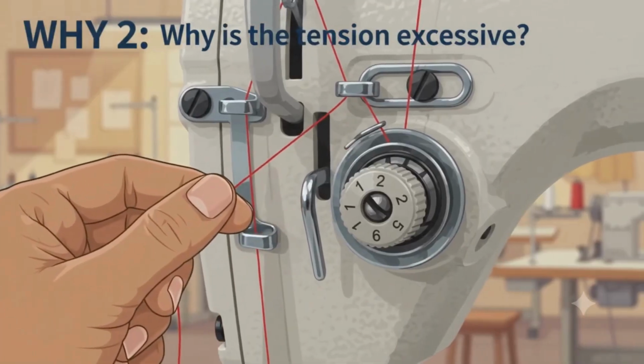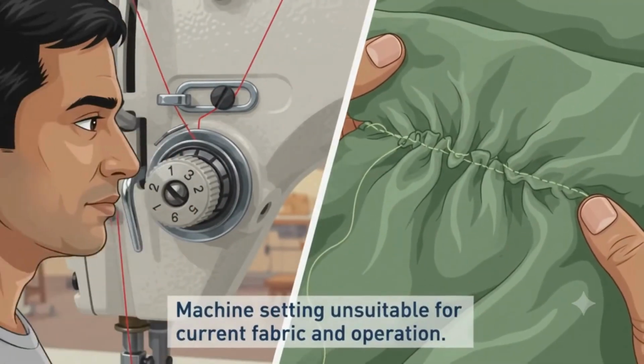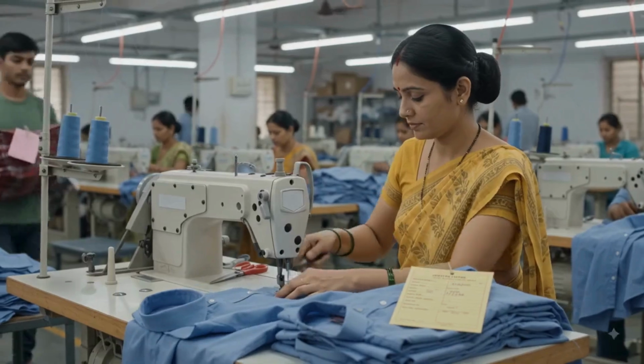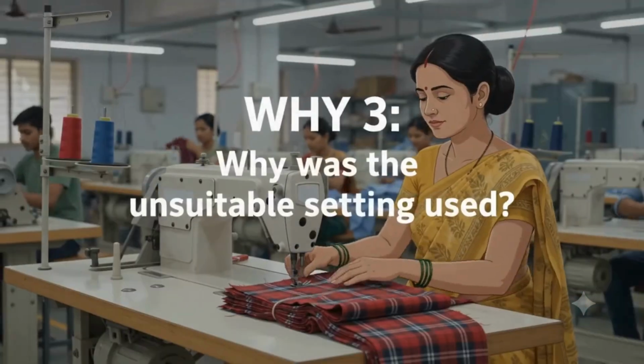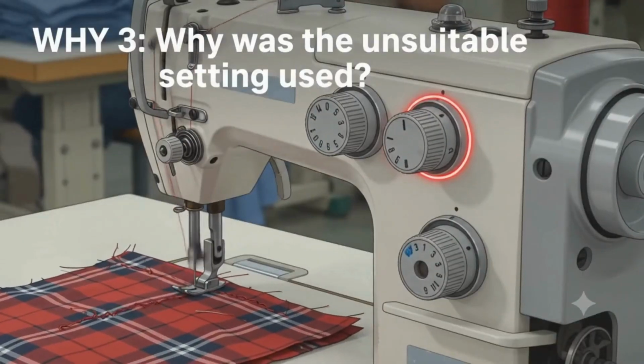Why is the tension excessive? The machine setting is unsuitable for the current fabric and operation. Why was the unsuitable setting used? It was carried over after a style or fabric change.